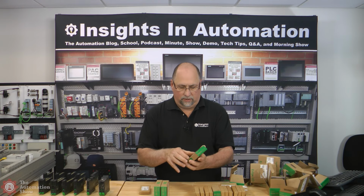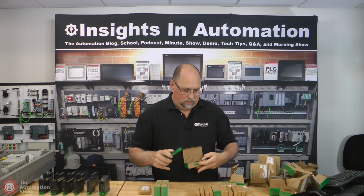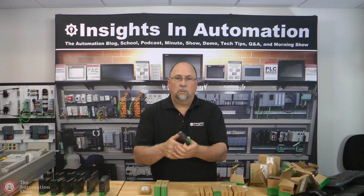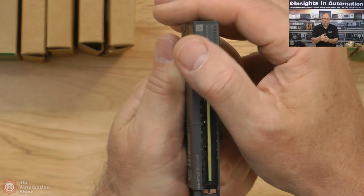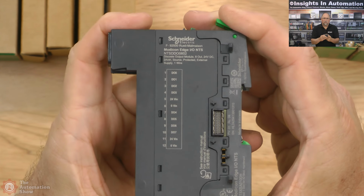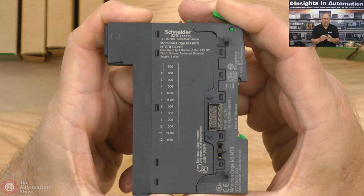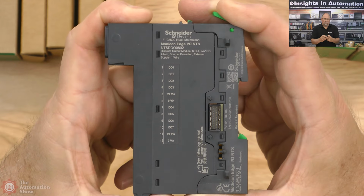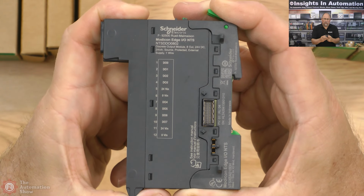What else have we got? Okay. This is a DDO, so discrete digital output. Let's see what it says here. 8 outputs, 24 volts DC. Sourcing, protected, external supply.